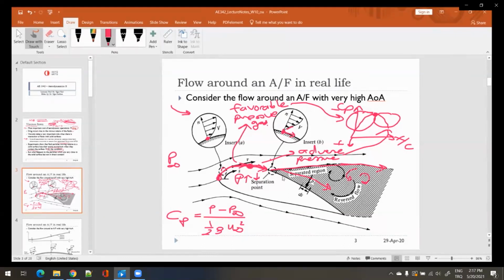On the airfoil surface where we have a separated region, the pressure distribution becomes almost flat, so it entirely changes the load on the aircraft, and the lift suddenly drops very quickly. All the physical phenomena that I described until this point, the generation of the boundary layer, the separated flow process, and therefore the consequence of having lift reduction, is all related to the viscous flow physics.